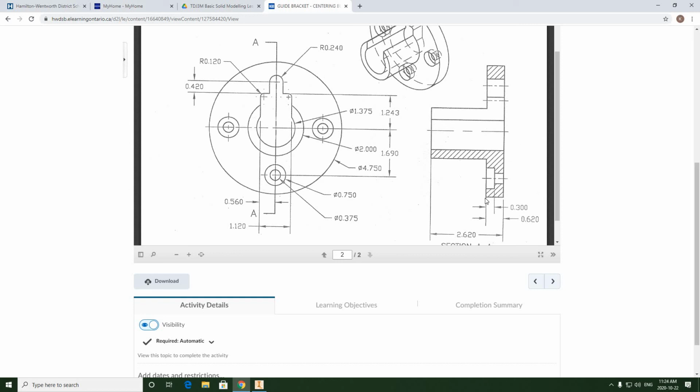It is a right side view, and it orthographically will project like the one that I just deleted, but it's called a sectional view, meaning we're imagining that we're cutting the centering bushing in half vertically from top to bottom, and the arrows here are looking in the direction of what we're looking at on the inside of it.